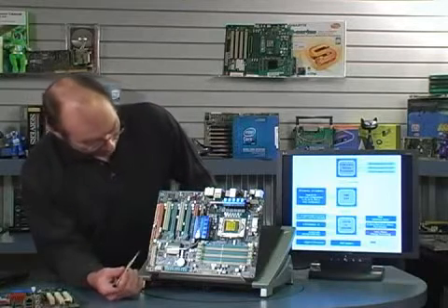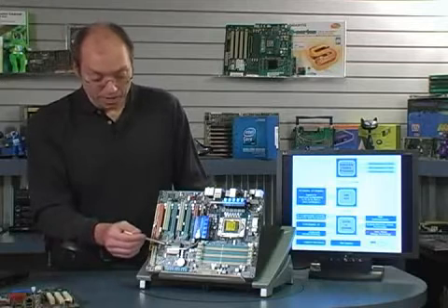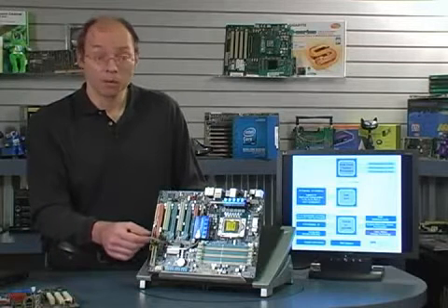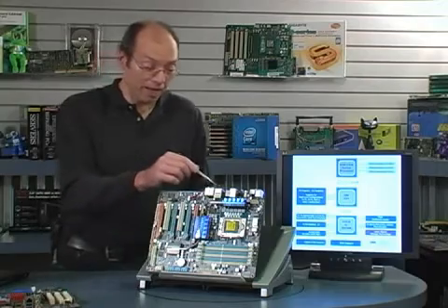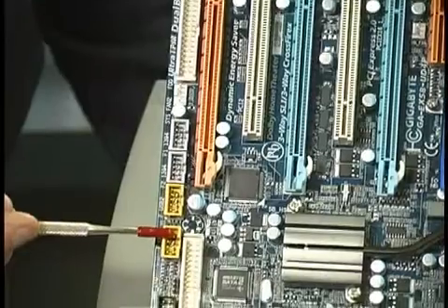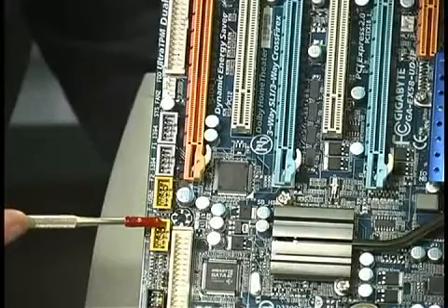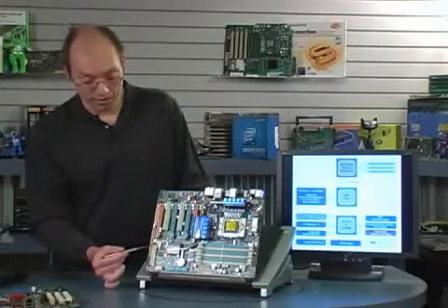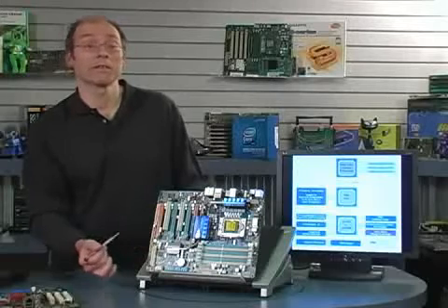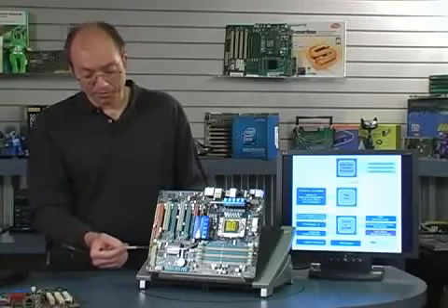This board has additional functions as well. Built into the South Bridge are also USB ports, 12 in fact on this particular chip. So we have 8 USB on the back, and we have 2 USB headers here. These are designed for front panel USB ports. Each of these headers supports 2 more ports. So you could have up to 4 front panel USB ports, and the cables for those would plug into these